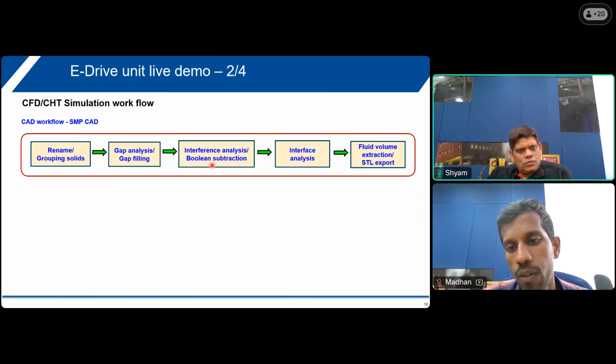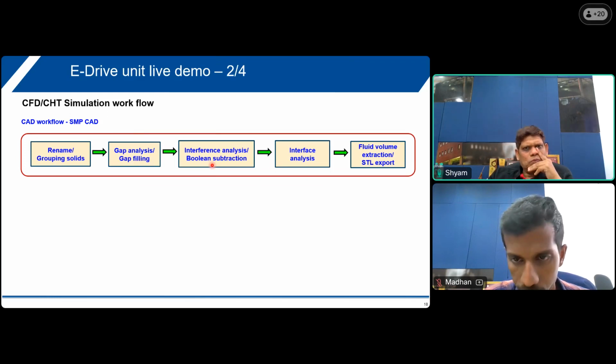If the interface between the stator windings and the liner material is not captured, then the heat transfer between these two components will not be captured correctly. When we are not capturing this heat transfer correctly, it can give rise to incorrect temperature prediction. That's why it's always important to capture these interfaces correctly, so that the temperature distribution that we predict from our simulation will be correct.